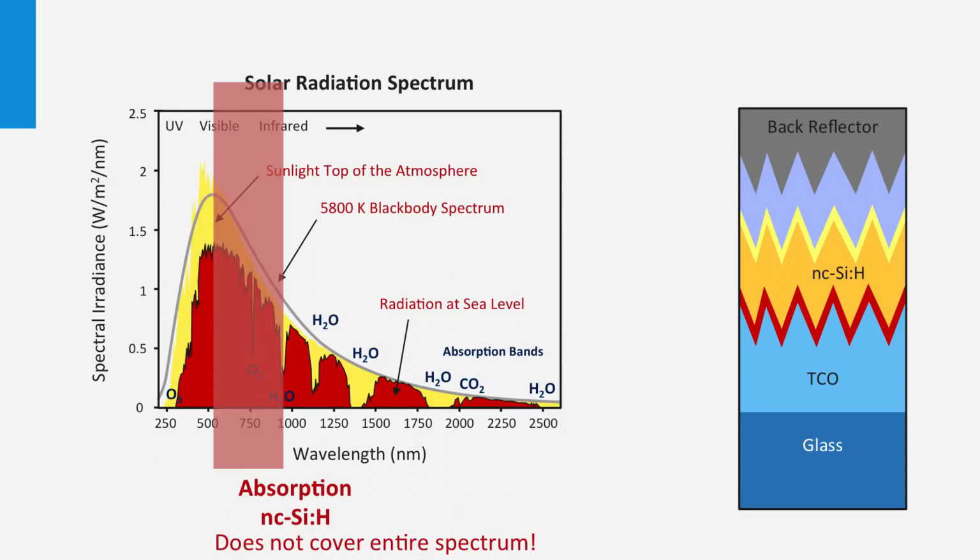Nanocrystalline silicon films are used as intrinsic absorber layer as well in a PIN solar cell. The spectral utilization of the nanocrystalline silicon PIN junction is better in reference to amorphous silicon due to the lower bandgap of the nanocrystalline silicon. However, to utilize the spectral part from 700 up to 950 nanometers, thicker films are required. Typical intrinsic film thicknesses are 1 up to 3 microns of nanocrystalline silicon.